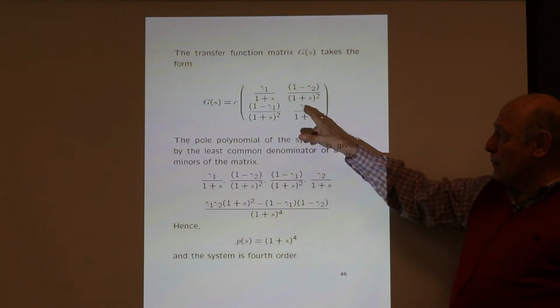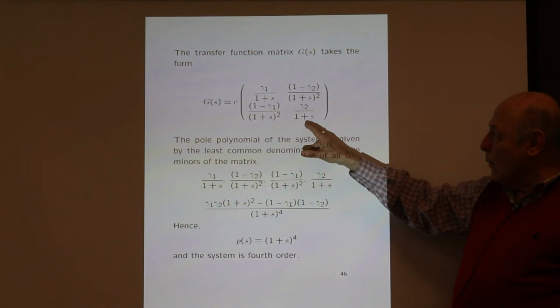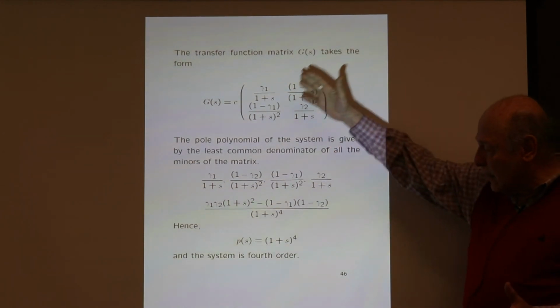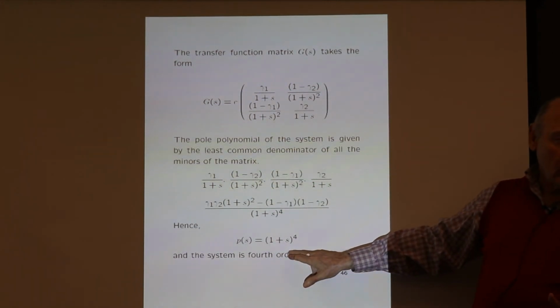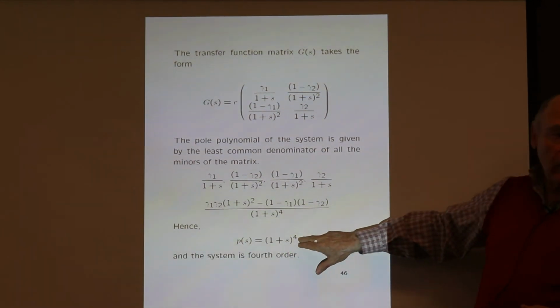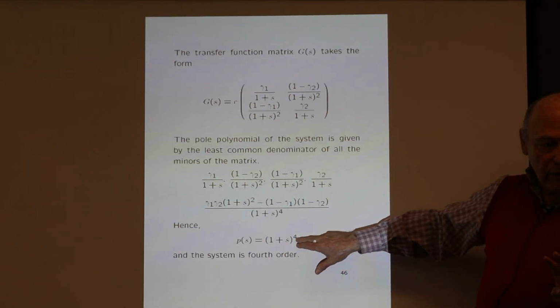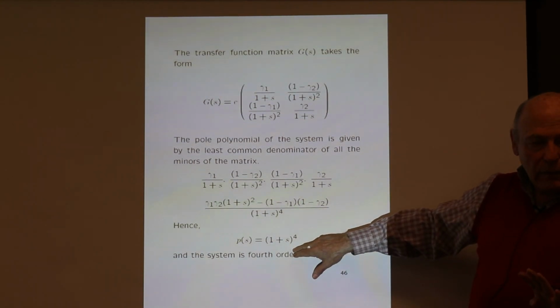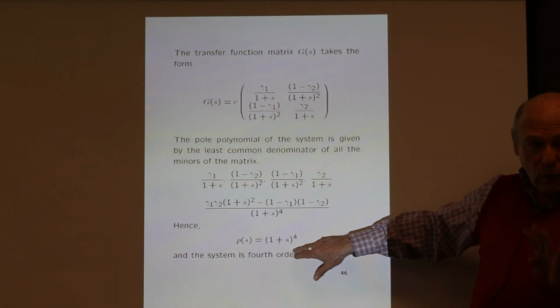So in doing so, you simplify the problem. Yeah, I simplified the model. They're all the same time. Yeah, we simplify the model. They are the same, but nevertheless, you have 4 poles. It doesn't matter if they are equal. You have 4 poles, and the order of the pole polynomial is 4, even though all the poles are located at -1. That's okay, but you have 4. You don't have 1. You have 4. That's the simplification.